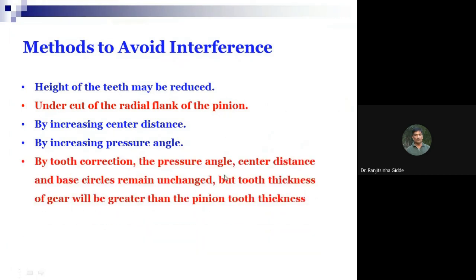Next you can write, by tooth correction. Another method is through the tooth correction. By tooth correction, the pressure angle, center distance, and base circles remain unchanged.